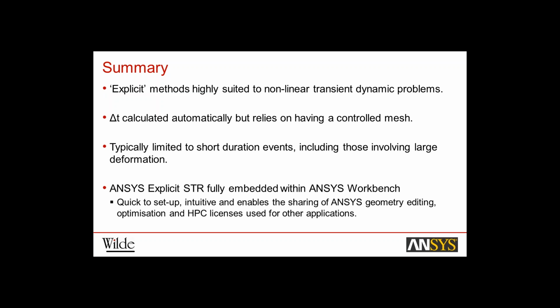Obviously, due to the nature of the explicit method, it is typically used for short duration events, as you've seen, but also it can be used, and certainly we have used it in the past, for those involving highly demanding deformation, such as in metal forming and in large compression of rubbers. And there's some techniques, including mass scaling, to help with that.